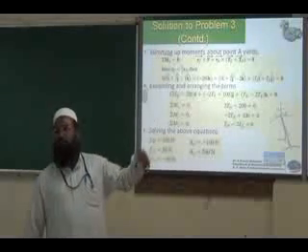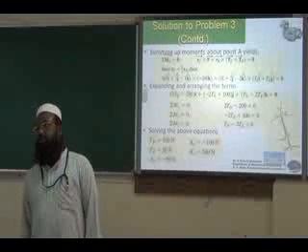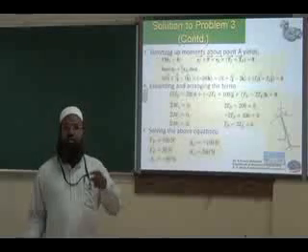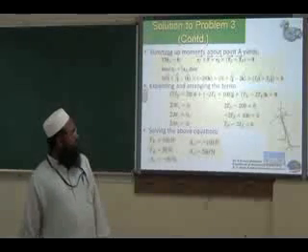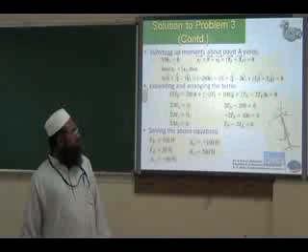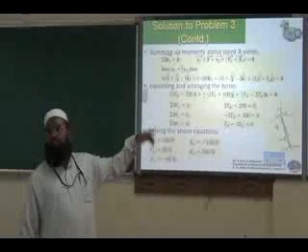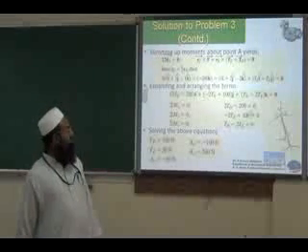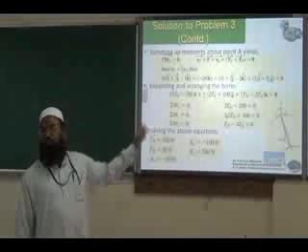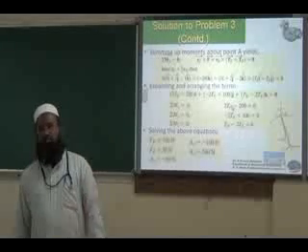So we use the cross product approach to find the moment of the force at point C and the moment due to the tensions. In the cross product, we can use any line connecting any two points on the forces. We want to find the moment of this force about A, so we can take any distance. It can be perpendicular, it can be parallel. So we assume it is parallel to the rod. We just find the position vector along AC and along AB, and find the moment using the cross product approach, splitting the equation into I, J, K components. We got three equations of moment and solved for the unknowns. That is the easiness of the Cartesian form and cross product approach. We need not find the angle, which is difficult to find.